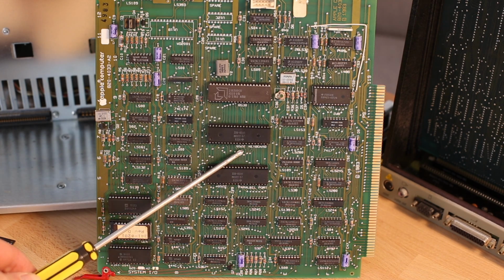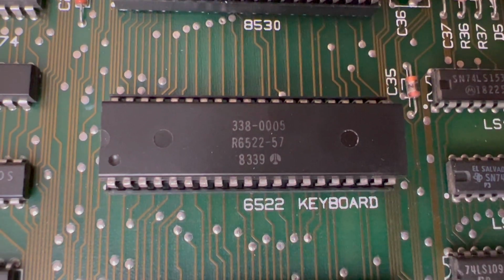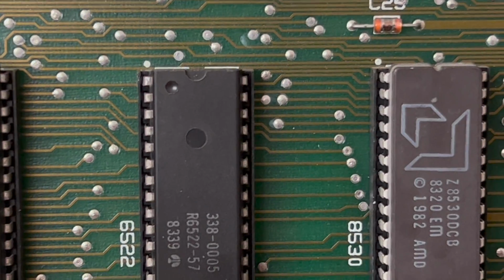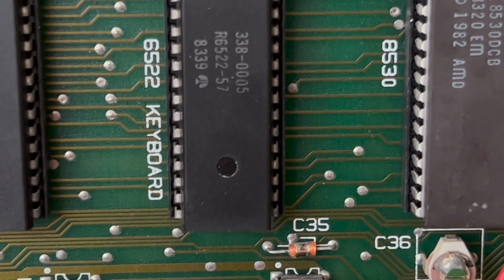Sound is generated by first pre-programming the 6522 to enable continuous shift-out. Continuous or rotational shift-out works by taking bits 0 to 7 from the parallel data bus and outputting them in a serial manner on the CB2 pin continuously. That is, the most recently output bit goes back to the end of the queue.